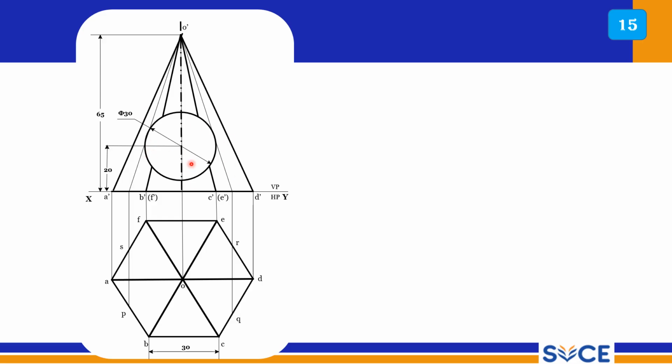Those points can be marked directly, but we have to measure the points from the true slant length. This is the true slant line; from there only we have to measure. So this is point number 1, point number 2, point number 3, 4. On this reference line it is 5, 6, 7 and 8. So totally 8 points, and these 8 points we have to obtain on the other side as well. You mark 8 more points, so totally we are getting 16 points. Those 16 points we have to mark carefully.